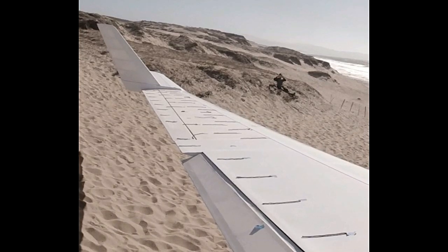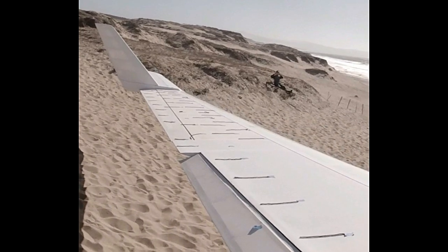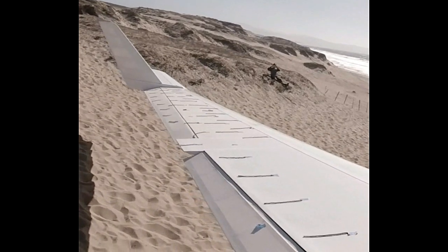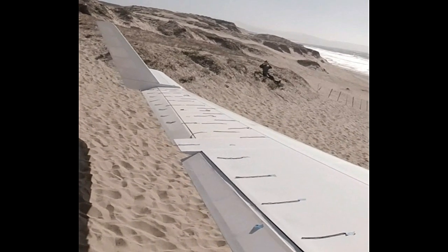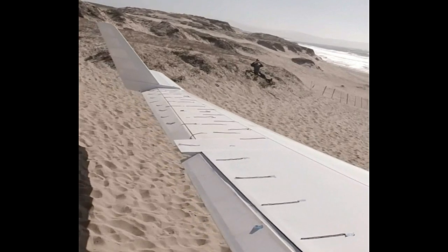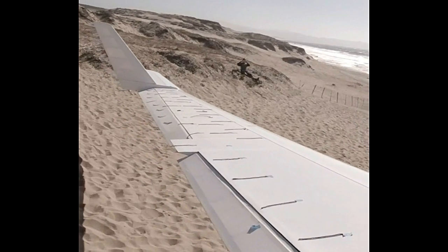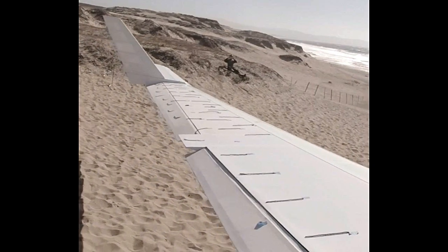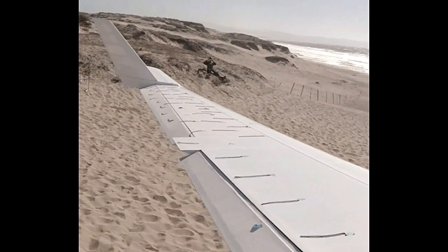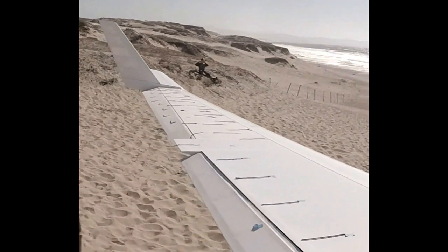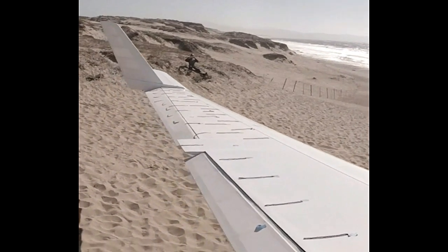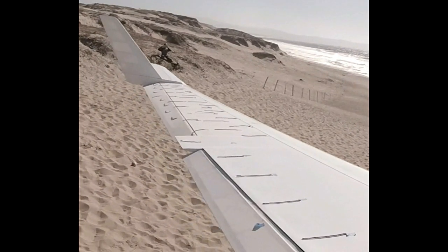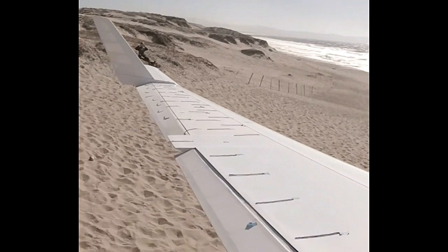But as long as the elevon is straight back like that, no angle of attack, the flow looks very good. And here I'm moving. Elevon comes down a little so I can pick up that wing. That wing had started to drop, and there we see the flow build up spanwise on the aft portion of the elevon. So it is clearly separated, and that's a bit of a problem because that generates a lot of extra drag on that side and causes me to want to yaw to the left, which is the last thing I need at this point.